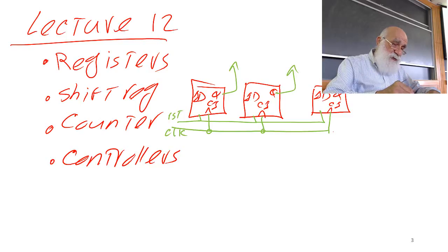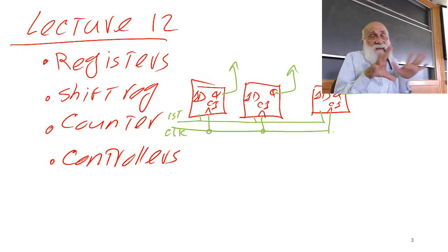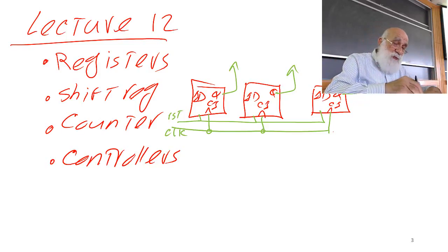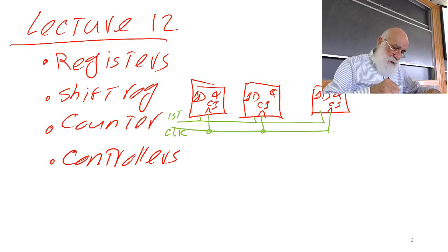If you have a situation like this, this is a 3-bit register. The outputs are shown there. Usually I use a different color for the clock and reset, indicating that clock and reset are things that you don't touch, you don't play with, and they don't come into your design procedure. And so this is what we can call the register.